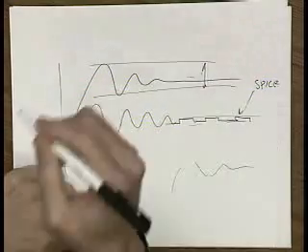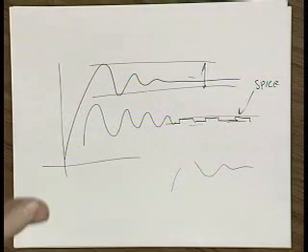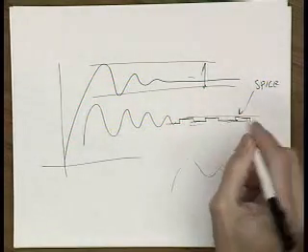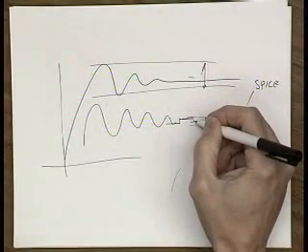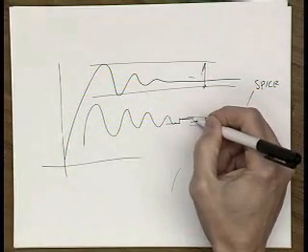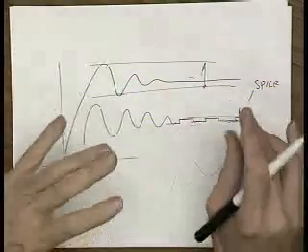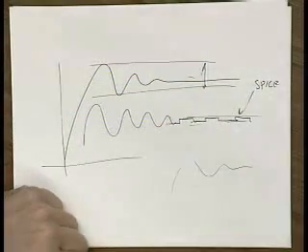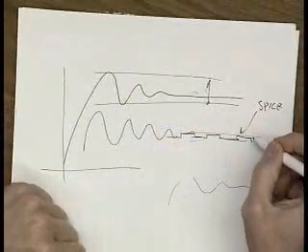Basically, SPICE looks back at its last answer and sees if things have changed by a certain amount. If it's changed by less than an error tolerance, then it says it's converged. So it looks for convergence by seeing how big the final wiggles are. It's always jumping back and forth a little bit. The question is whether that is small enough relative to your accuracy requirement. That tolerance you should make 10 to 100 times smaller than the absolute value you're interested in having. There's a spec we're going to put on the newsgroup soon today,